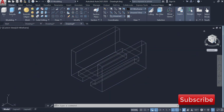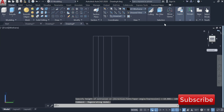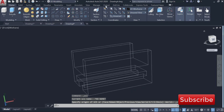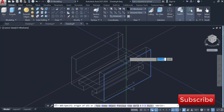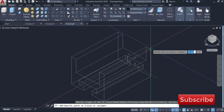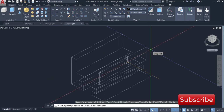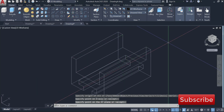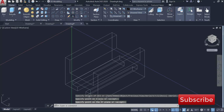So let's switch the view. Let's make it the XY plane, this one, and then let's move our UCS to this point. Look, XY this direction, X axis to this direction, and Y axis to this direction. And I hope you can see it.